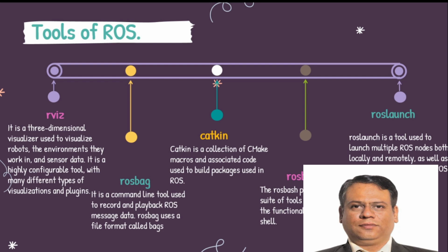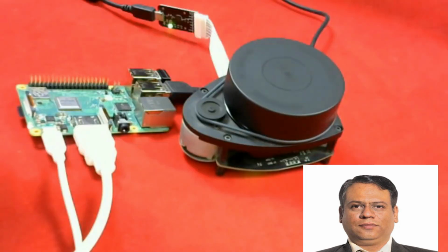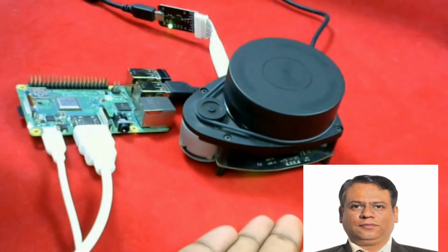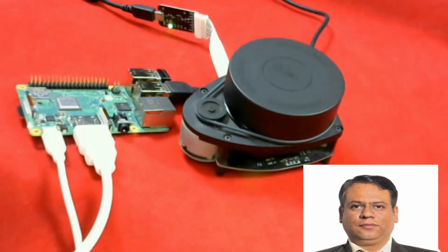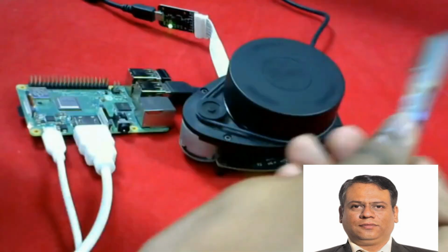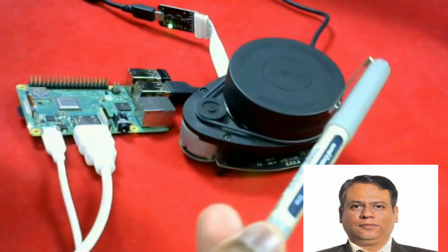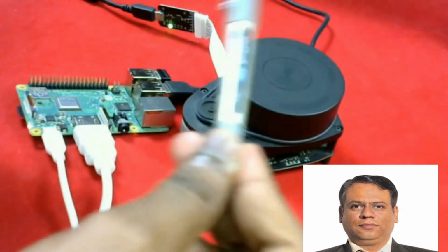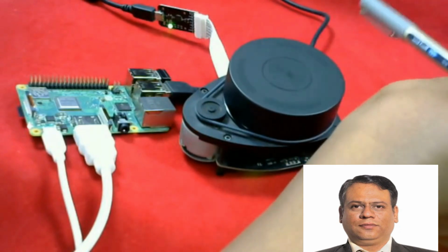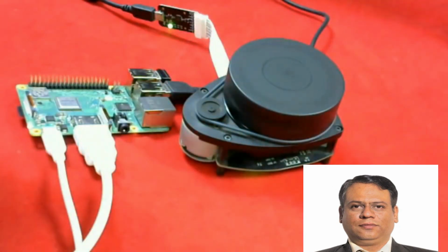Okay, so I hope you have explored the Robot Operating System a little bit, starting with the RPLidar. In this video, the RPLidar has already started rotating. The RPLidar A1 has a certain module, the black module, present here. With the help of that module, the RPLidar is connected to this Raspberry Pi using this black USB B type cable with the filters. That's all for the connection. Other than that, it doesn't require any other connection.